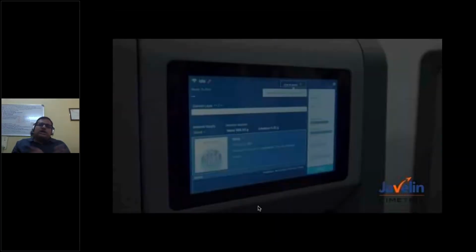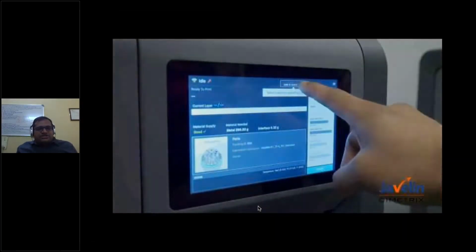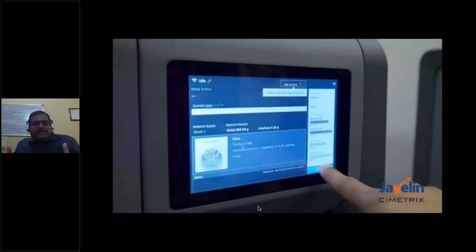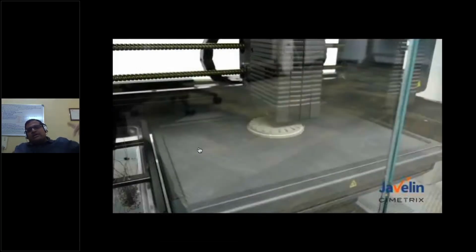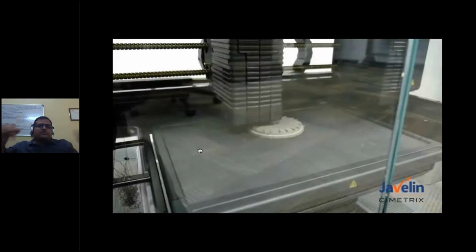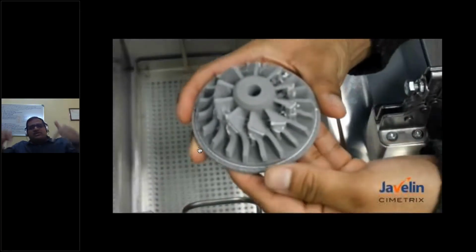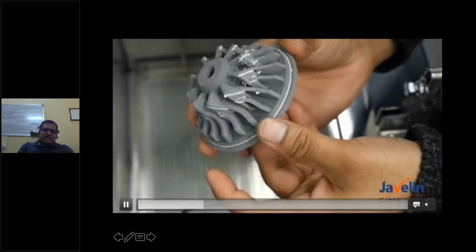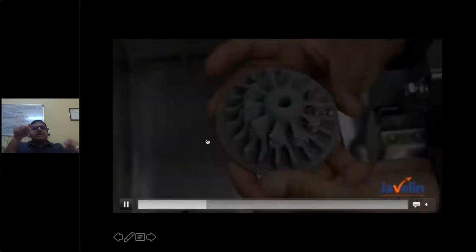Of course, it should undergo a sintering process, and it must have debinding, followed by sintering. You can see the raw material is taken in, the metal rod one, and another one is the support material. So you have one rod and one support; this is the model and this is the support, and you make them differently.